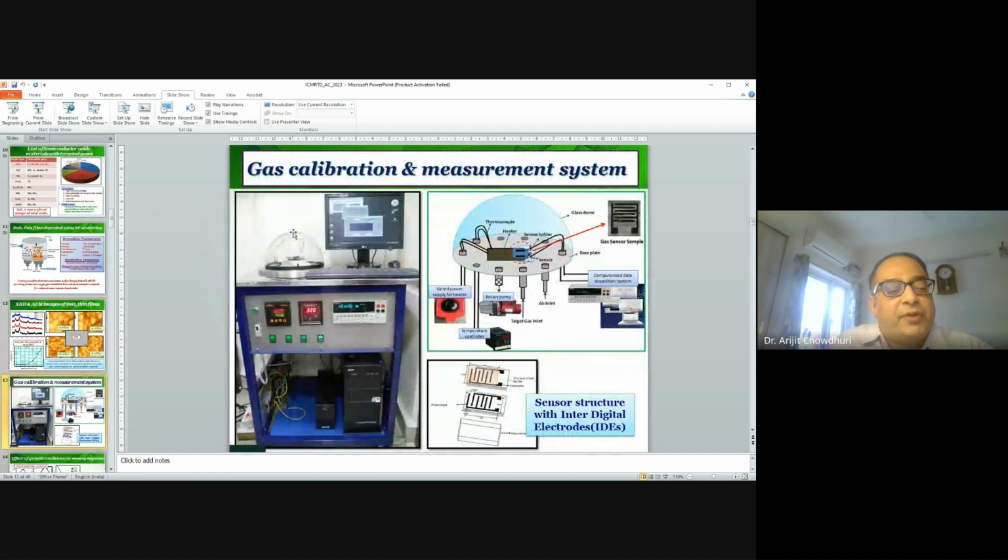For gas sensing, of course, we use this customized gas sensing test rig, which had a computer-interfaced Keithley DMM. And we had a chamber which could actually simulate real-life conditions. For example, we put in zero-grade air, and we put the target gas in through a specified calibrated leak. And we took the measurement characteristics, including sensing response, the response time, and the recovery time.